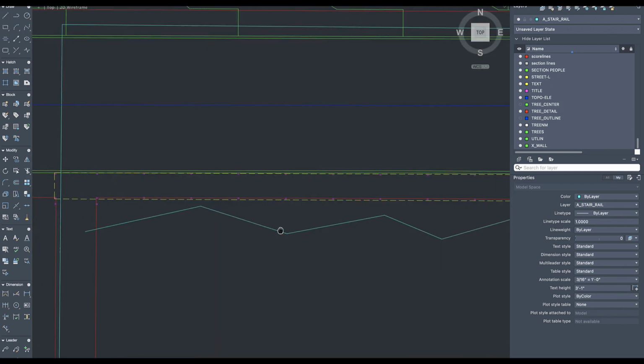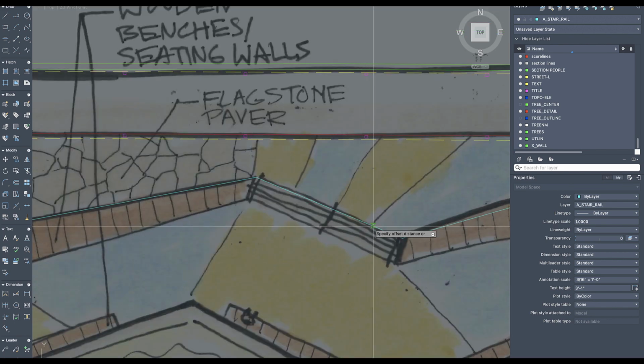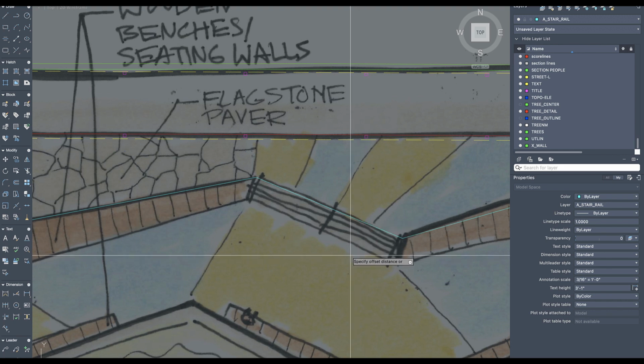Now there's a few areas where we're going to directly offset from these lines. The stairs will be one example. We'll offset this 12 inches. Maybe that's our tread that we're going to use, although this is at a school. It might be that our risers are going to be something closer to a 4-inch riser. Just because we will have kids here, and if we're using our tread riser ratio, we'll do 2 risers plus 1 tread around 24 to 26 inches.